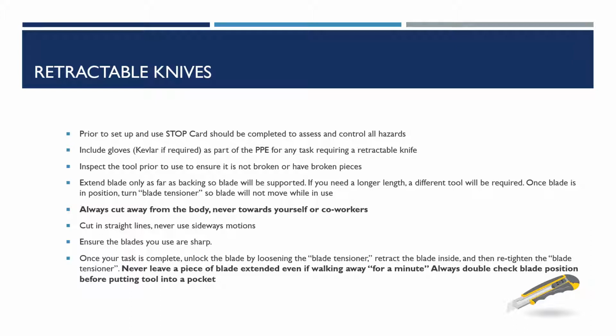Always cut away from the body, never towards yourself or coworkers. Cut in straight lines, never use sideways motions. Ensure the blades you use are sharp. Once your task is complete, unlock the blade by loosening the blade tensioner, retract the blade inside, and then retighten the blade tensioner. Never leave a piece of blade extended, even if walking away for a minute. Always double check blade position before putting tool into a pocket.